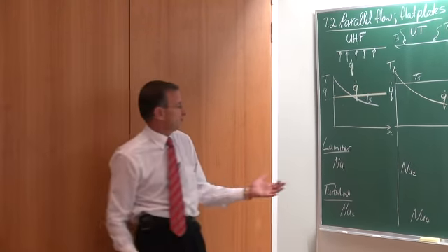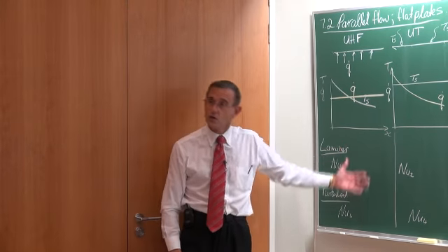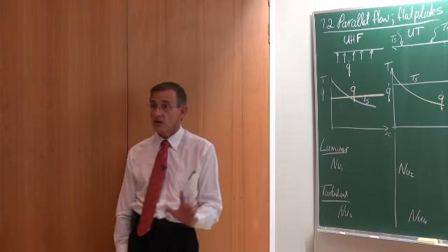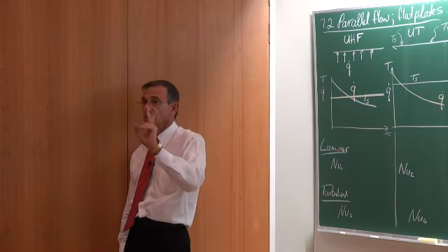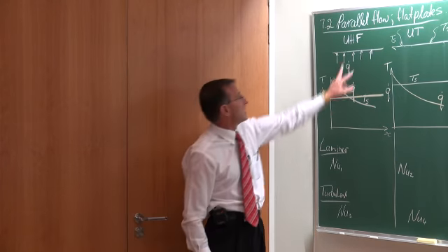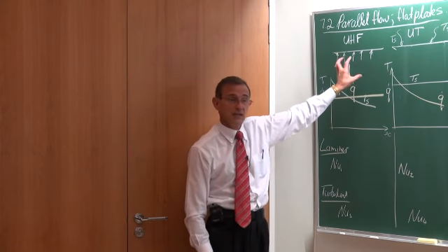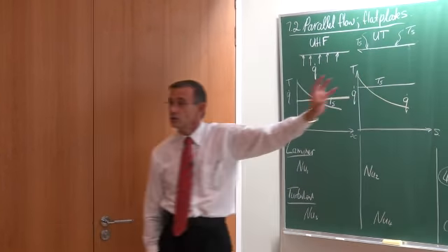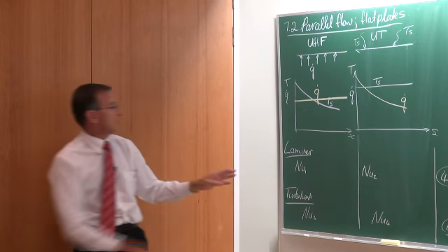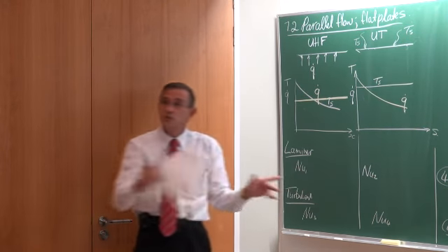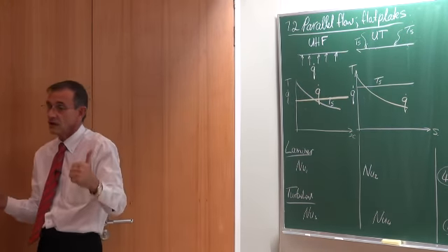You have to determine, is the flow laminar or turbulent? If it's laminar, then you must see red flags. Very, very important: is my application one with a constant heat flux, or one with a constant wall temperature? Immediately you have to distinguish between the two different Nusselt numbers.